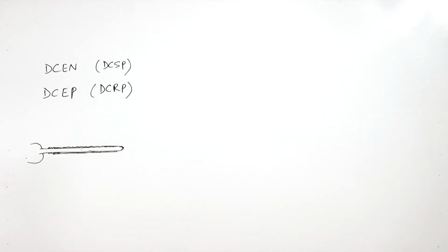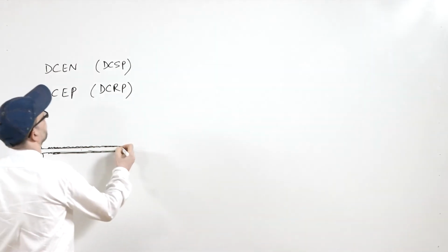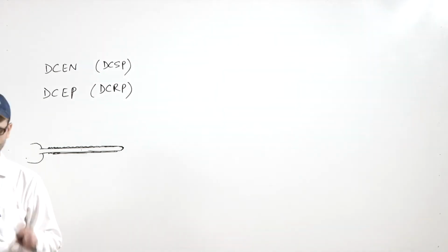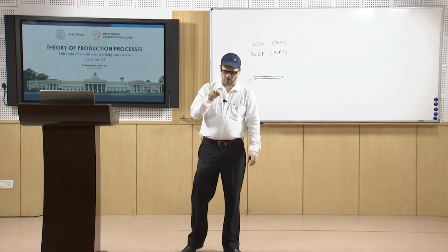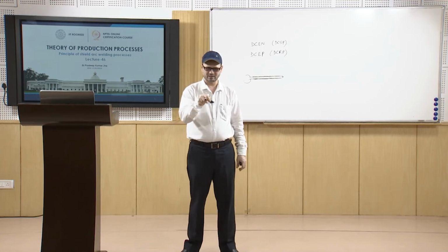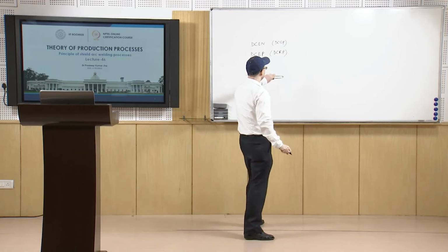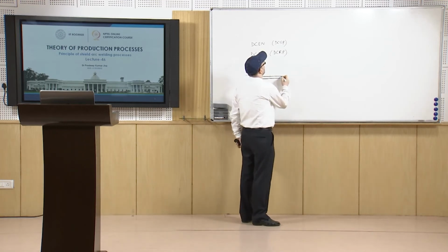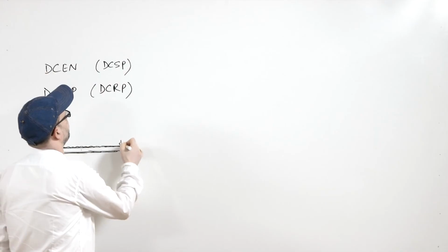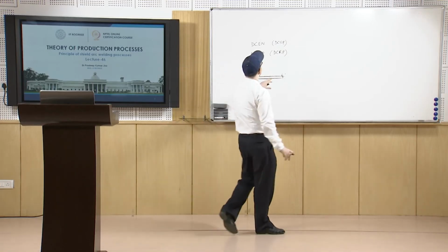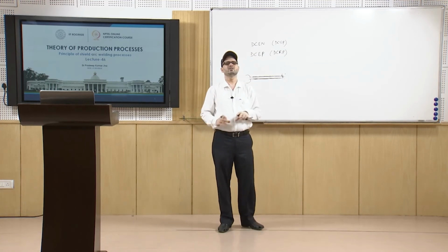One of the functions is that it helps to direct the arc towards the weld pool, towards the metal where the placement of the metal itself is. Otherwise, if there are no flux coatings, these arcs may go in all directions, so there may be a large amount of loss of heat from the arc due to radiation in all directions.